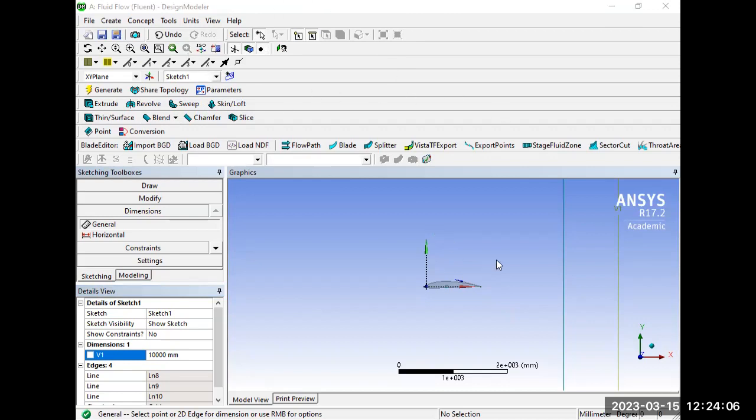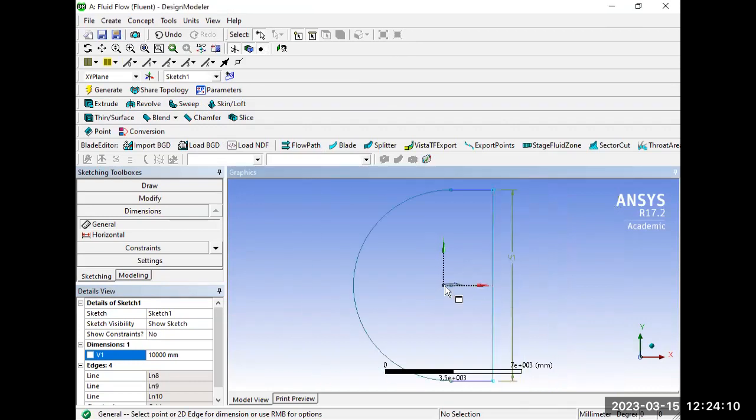So now you can see from here as my domain. When I'm zooming it out, you can see this length is sufficient. This top portion from here to here, there is a sufficient gap. So if I'm making the air flow from this side, the walls will not affect the aerofoil. So my gap is enough here. But my length is not enough to find the flow.